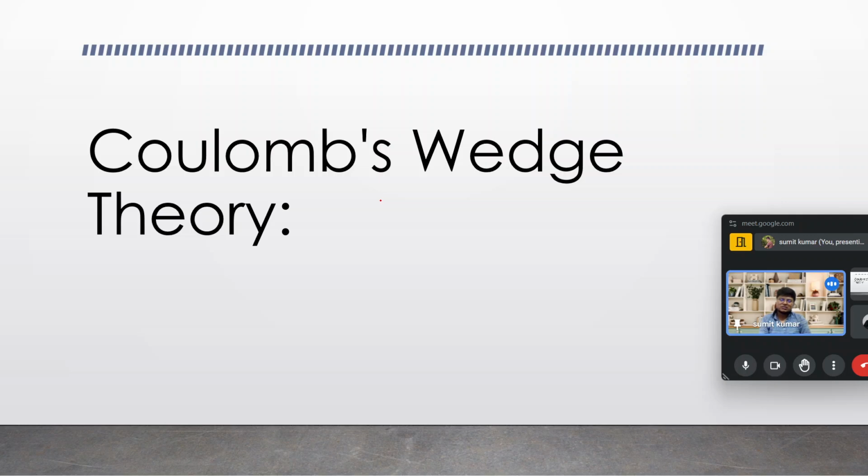There, under the Rankine column, we discussed the Rankine earth pressure theory for the active and passive states, and its modification for cohesive soil, which considers 2c root k and minus 2c root k for the passive and active states of stress respectively.